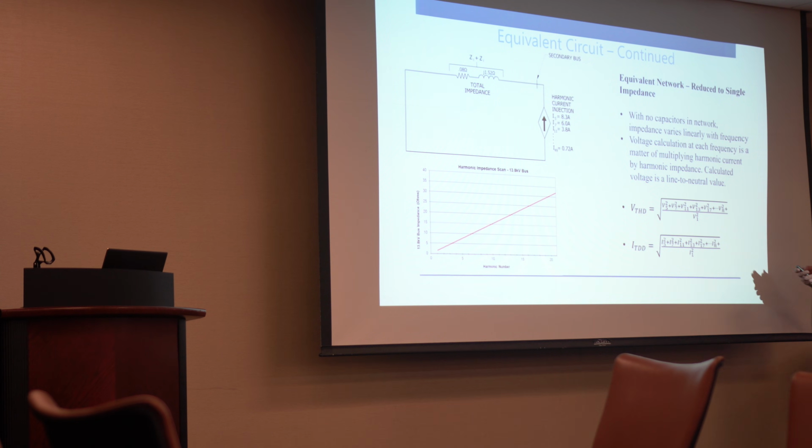When we're all said and done, we can take those impedances and combine them into one. We add the R's and add the X's separately because it's a phasor quantity, a complex impedance. You can't add the R's and X's together, they're separate. So we have 1.52 as the X component and 0.08 ohms as the R component. It's a very simple series circuit when we're all said and done.